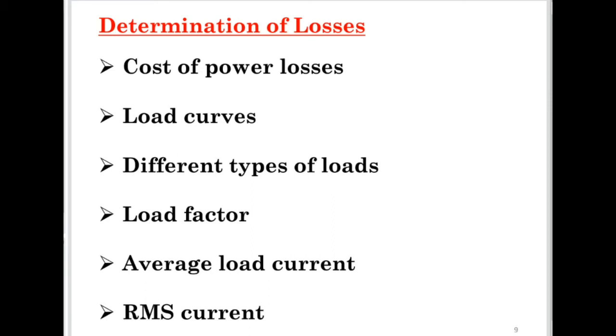So we consider DC and AC equivalents in terms of amount of charge transfer. But when we come to RMS current, we again go for AC and DC, but we don't consider charge transfer anymore. We consider the amount of heat generated. So we put DC, how much heat is generated. We put AC, for the same heat to be generated, how much current do we need. That current is RMS current. Is it clear now?